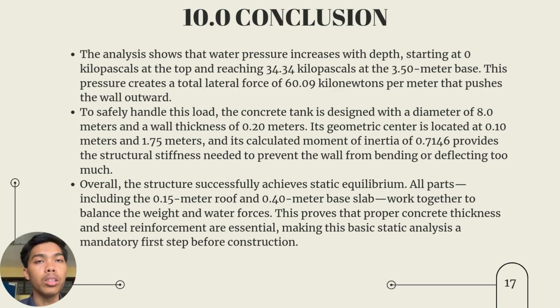So now we go to the conclusion. Our analysis showed that water pressure increased with depth, starting at 0 kilopascal at the top and reaching a maximum of 34.34 kilopascal at the 3.5 meter base of the tank. This creates a total lateral force of 60.09 kilonewton per meter that pushes the wall outward and generates a bending moment at the bottom.